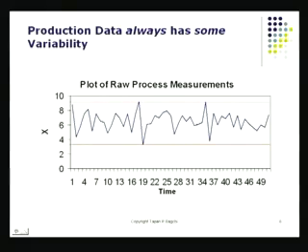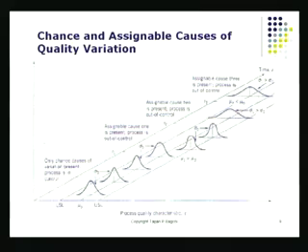Both of those things are important, certainly for the user. The final user who's going to be using the outputs that I produce out of a process, those have got to be accurate and also precise. I cannot really control these two aspects of quality, accuracy and precision, just by using the raw chart. It's not possible. I have to convert this raw data into something else, and I'll show you exactly what I do. In fact, this is the heart of statistical process control.